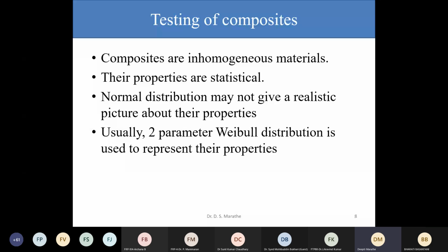So what do we usually do? Say if I've decided to carry out a tensile test for some metal, or for, say, some polypropylene sample, I take 5 or 8 test specimens. I get the values of tensile strength and tensile modulus. And what I do, I take an average, meaning that I assume normal distribution. I take the average and I report the average and standard deviation.